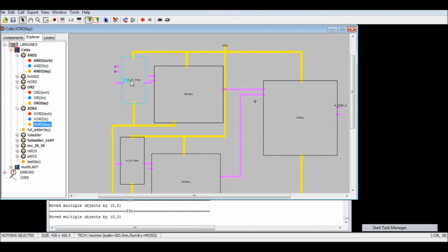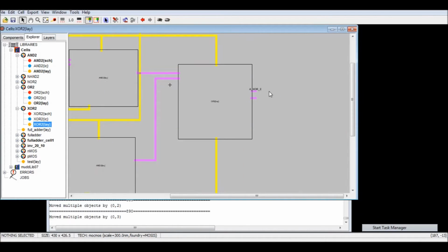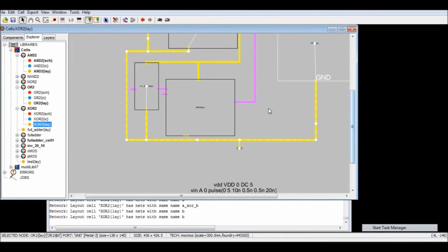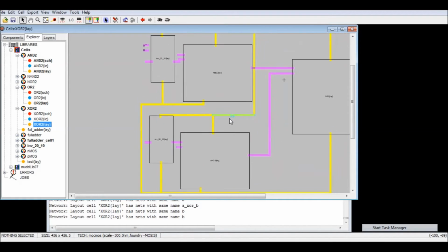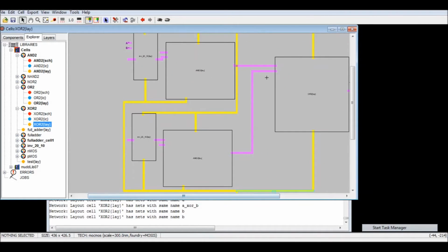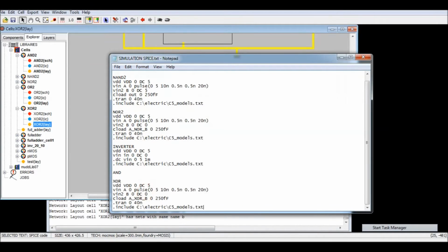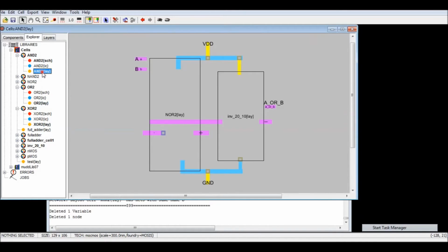Here I have B inverted ANDed with A, then A inverted ANDed with B. All of them are ORed together, and I'm getting the output here. And let me see, yes, okay. Yeah, and the ground rails are all connected, I think. Only this one is not. And yes, to simulate it, you can use this SPICE code. I'm going to copy it into my archive. Okay, cool. Just delete it. And then this is my OR gate, my AND gate.